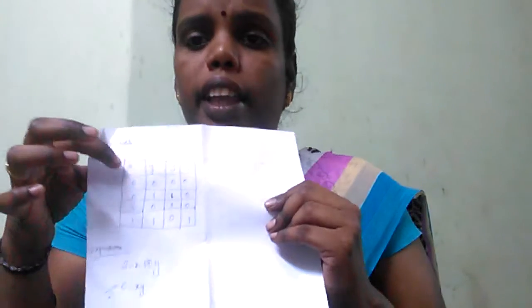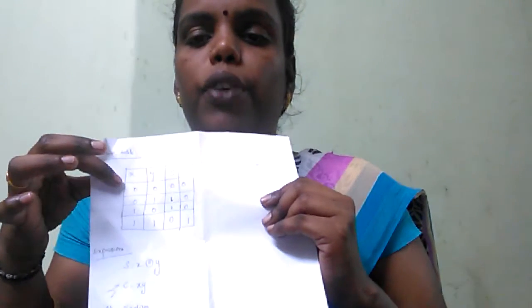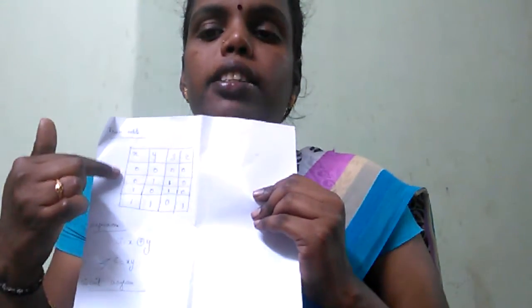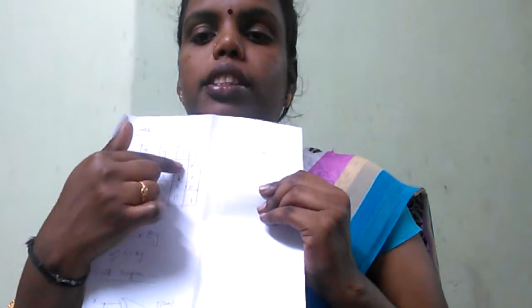These two inputs produce four possible combinations of inputs from 0 to 3, that is 0 0, 0 1, 1 0 and 1 1. This is the truth table for the half adder. In that, x and y are designated as the inputs for the half adder, and s and c are designated as the outputs. If both inputs are low, that is x and y are low, the sum and carry will be low, that is 0, 0.